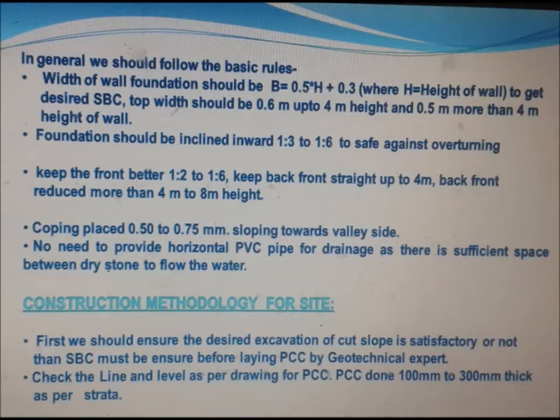Keep the front batter 1 to 2 to 1 to 6. Keep the back straight up to 4 meters; the back is reduced for more than 4 meters up to 8 meters height. Coping placed 50 to 75 millimeters, sloping towards the valley side. No need to provide horizontal PVC pipe for drainage, as there is sufficient space between the dry stones for the water to flow.